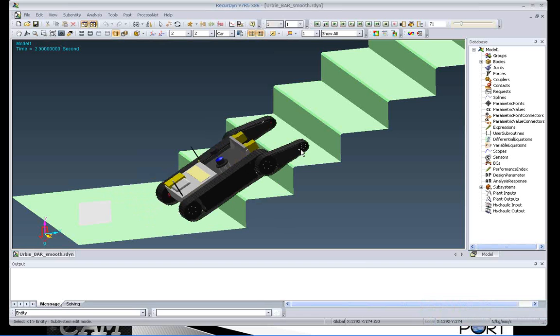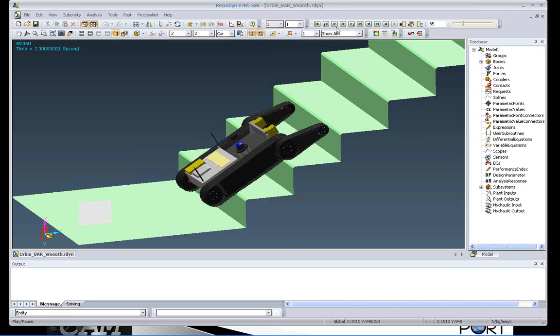So when you look at the load conditions, the other aspect is that certain parts of assemblies of interest, as you have different motions occurring, can again impose some of the higher loads. The idea is to use a product, whether it's RecurDyn or NX Motion, which can also do these kinds of motion simulations and calculate force.